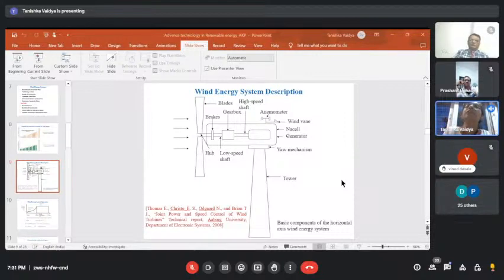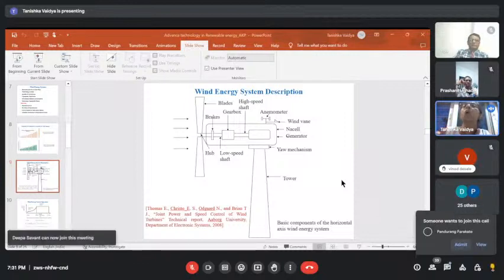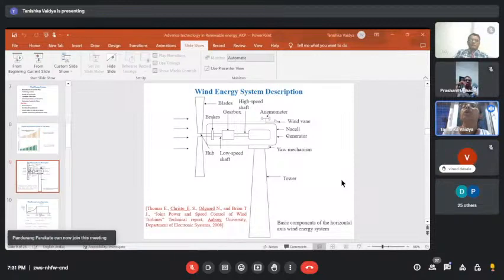So that pitch angle is controlled to maintain the optimum speed of rotation of this wind turbine. This is the first control. Then another is a torque control, and third is the yaw control, its direction. Here there is a motor which controls the direction of this nacelle or shaft towards the wind direction. So these are the major three controls, but further there is a tremendous amount of automation which is needed.